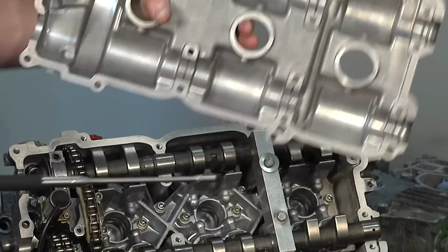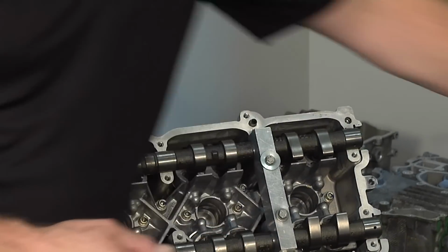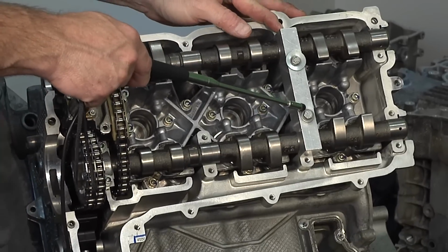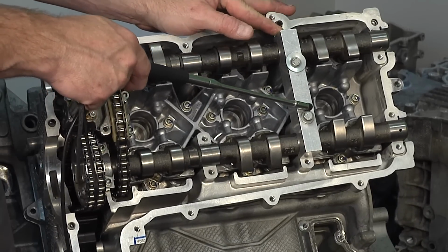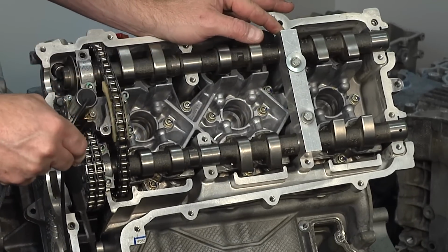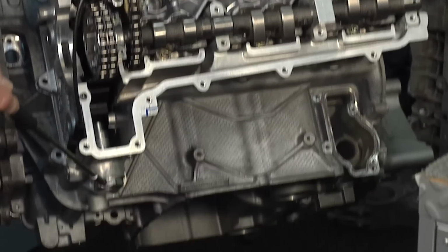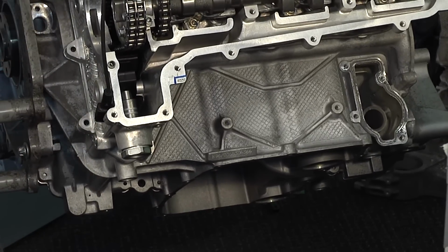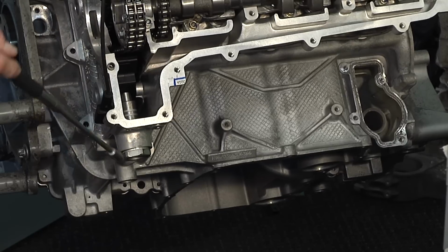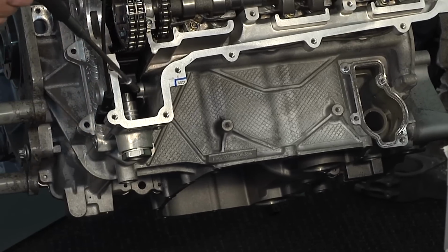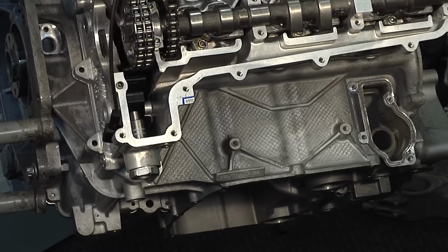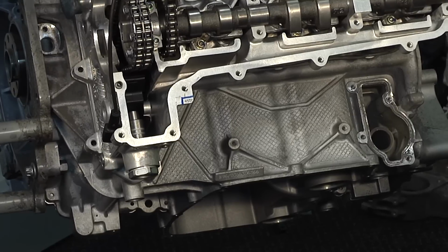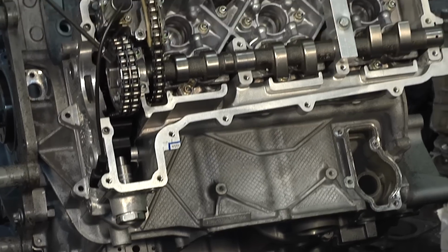So once that's off and you have this jig put into place, the next thing you can do is go ahead and pull your chain tensioner, okay? It's 32 millimeter, located on the bottom of bank 1 cylinder head, or located on the top of bank 2 cylinder head. You're going to remove this, and that is going to put some slack in the timing chain, okay? Once the slack is in the timing chain, then you can go ahead and remove the 4 bolts on the exhaust cam sprocket that you see here.